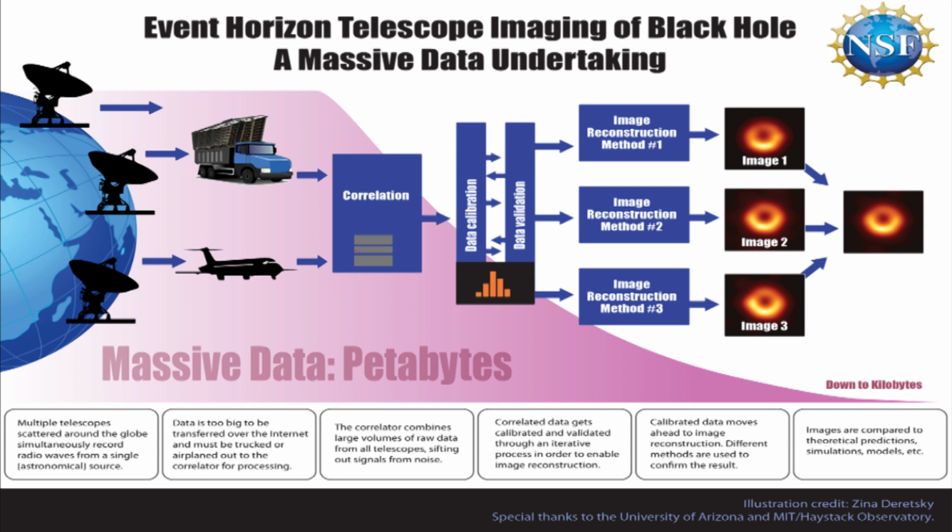And then the next step was something that took a lot of handwork, and that was to figure out what of this actual data could be used. See, there's a lot of errors that can creep up in doing this kind of process. Anything from atmospheric effects to slight variation in the Earth. The Earth will expand and contract every night, and so it will have some issues there. And overall, they just need to figure all of these details out so you can get the purest data to the image correlator so you can produce something that actually is meaningful.